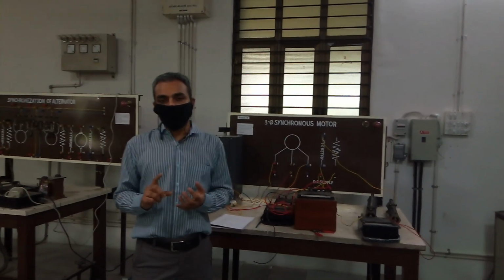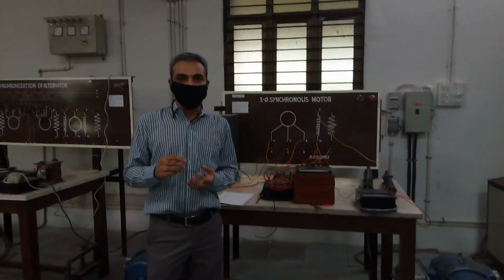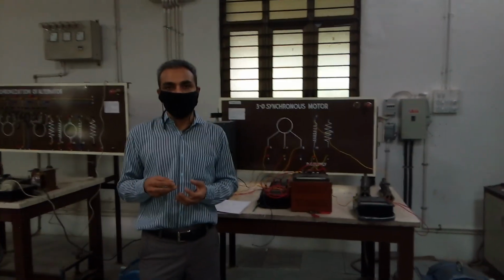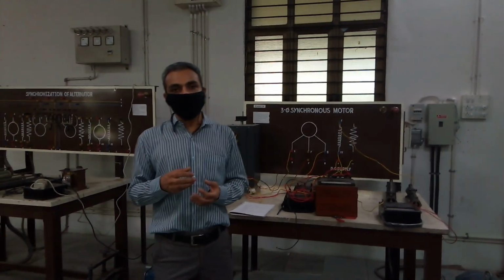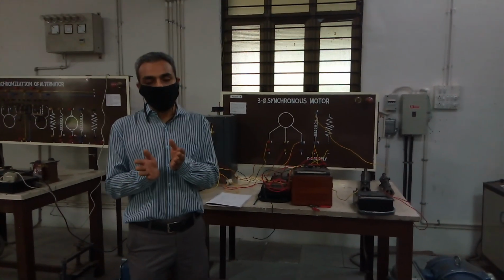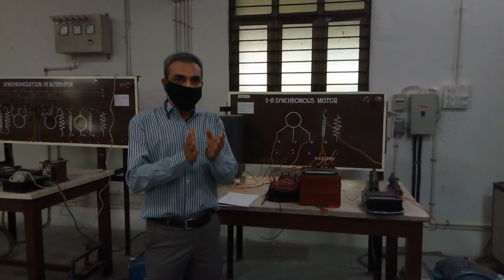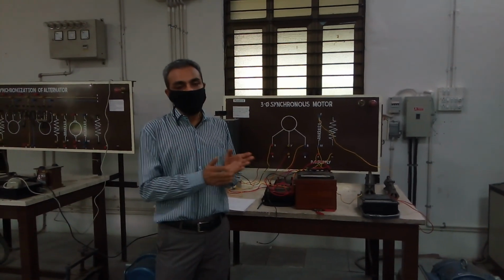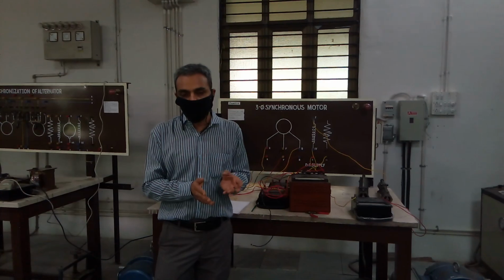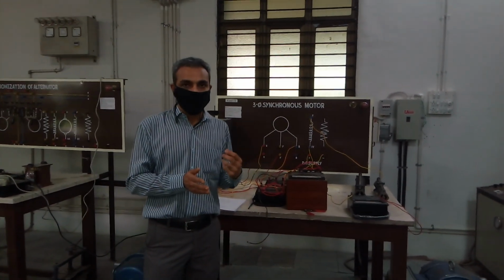If your machine is under excited, your induced EMF E is less than the supply voltage V, with some angle phi between them. Due to that, the overall power factor of the machine is lagging, and the machine will draw current from the source, right?